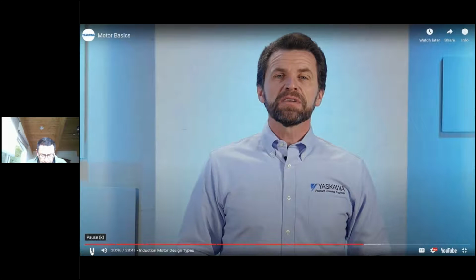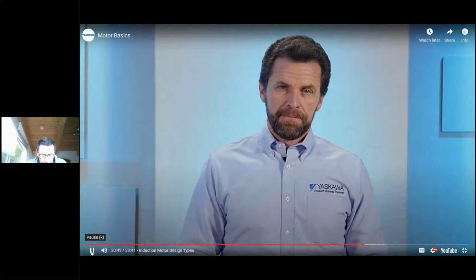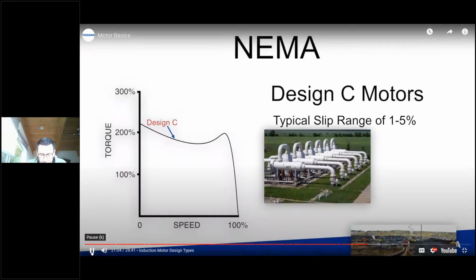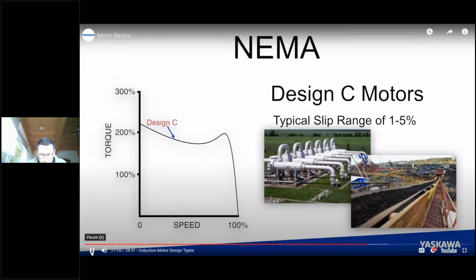Applications using NEMA Design A and B motors are best suited for drives, a topic that will be covered more in our next installment with Drive Basics. A NEMA Design C motor also has a maximum of 5% slip. Design C motors are built to power equipment requiring high breakaway torque, like positive displacement pumps and conveyors.